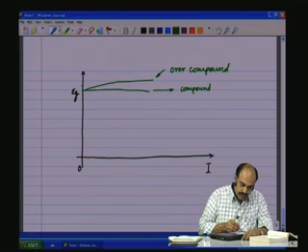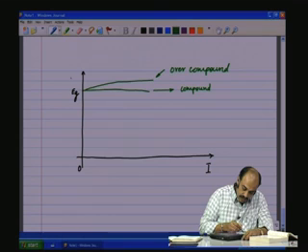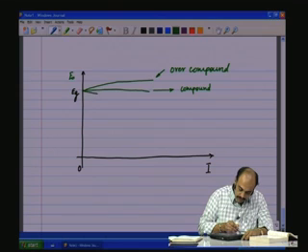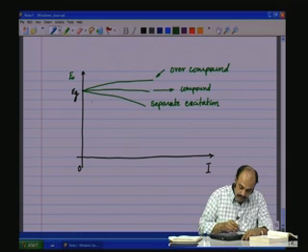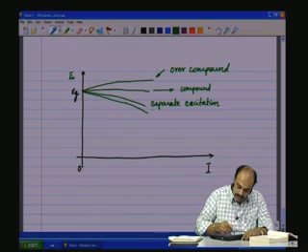And then in the case of the separately excited machine, with the load, the E naught value will dip. Let us say this is the separately excited excitation. If you have the shunt excitation, it is slightly poorer than separate excitation. This is the shunt excitation.